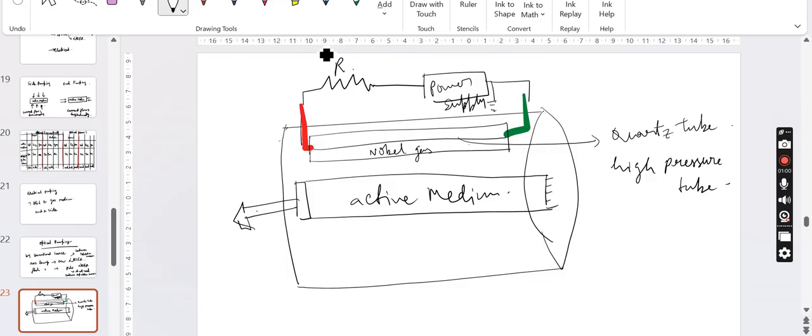The filamentation of the discharge results in greatly enhancing the density of the current flowing through it. This in turn causes the tube to emit light spontaneously all around it, intensely, much higher than possible with the conventional fluorescent light, making the arc lamp suitable for pumping a CW laser. The lamp, of nearly the same length as the active medium, is placed with the medium, and they are enclosed in a hollow cylindrical reflective cavity.